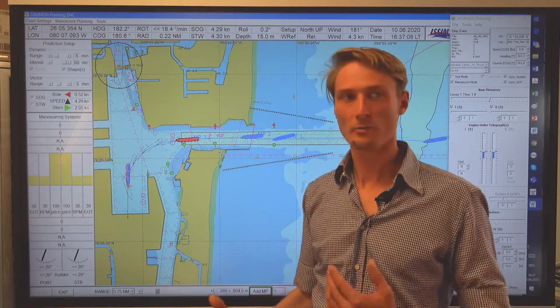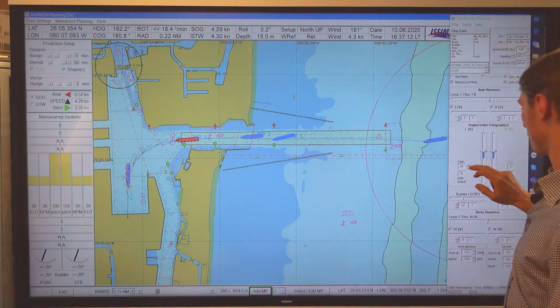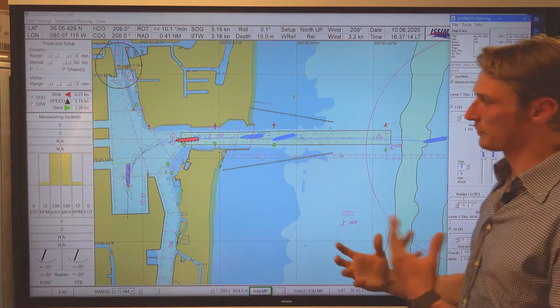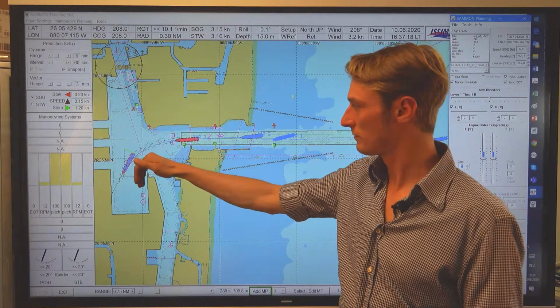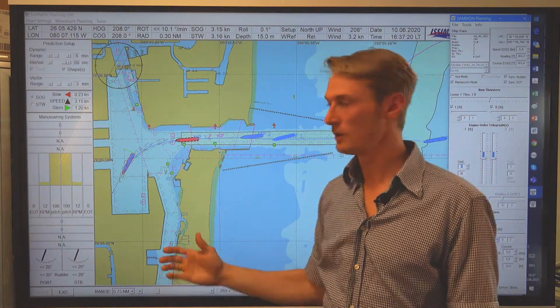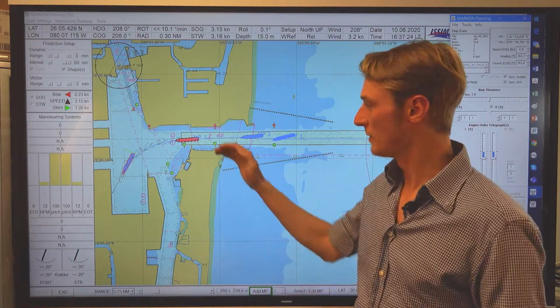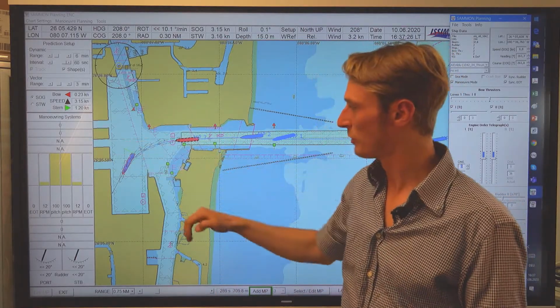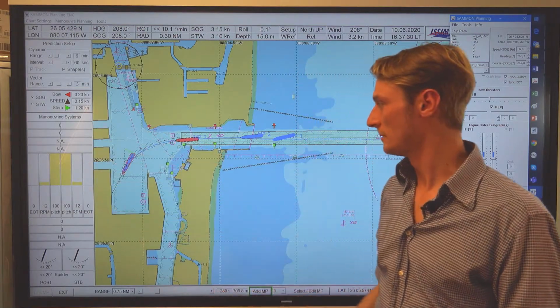And now, of course, I can combine it with reducing the engines. For example, if I had stopped the engines before, just to play through my options, my speed is dropping even further, but my turn is not that radical. So it's quite an open turn to port side, and I'm drifting further to the quay on the west.